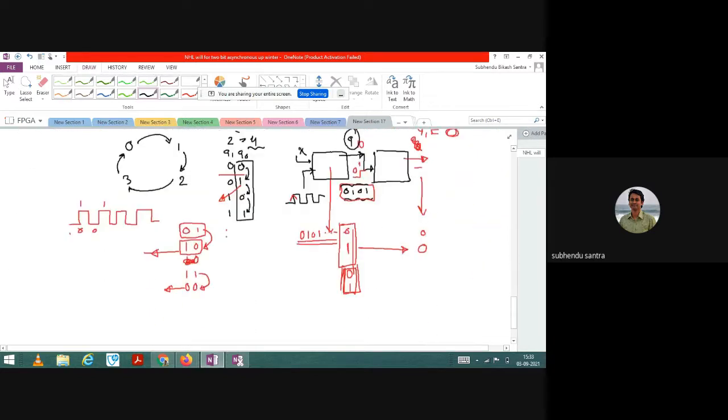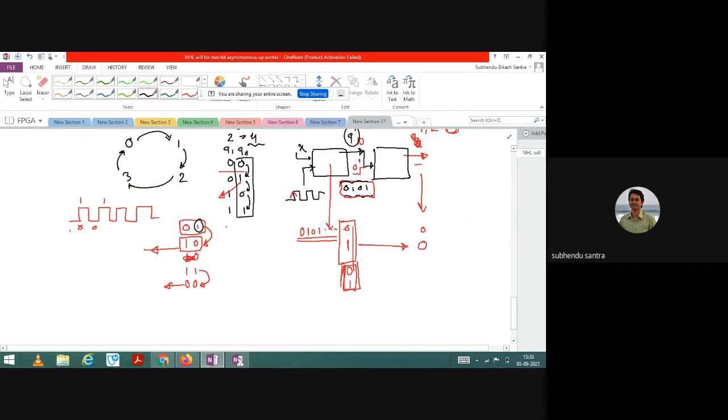I am telling you why. You see this 1 to 0, there is a change. Then once again 1 to 0, there is a change. Whenever the intermediate variable is changing from 0 to 1, q1 is not changing. This is q0, and q1 is not changing. But q1 is changing here. Whenever there is a 1 to 0, there is a change of q. And a similar thing happens here. Whenever there is a change from this position 1 to 0, then there is a change. So the thing is that it is just a NOT gate of the previous one, but the transition is not rising edge. The transition will be for falling edge. So that modification you have to do. So 1 to 0, here there is a change, and then once again 1 to 0, there is a change.